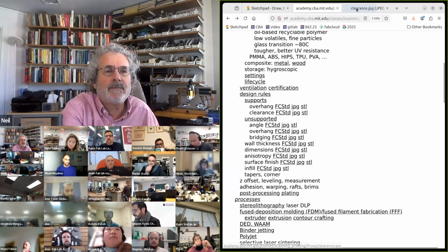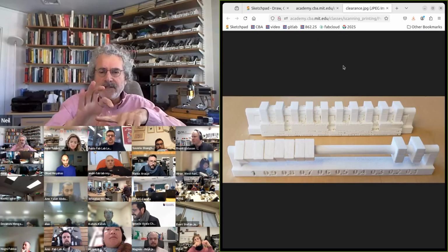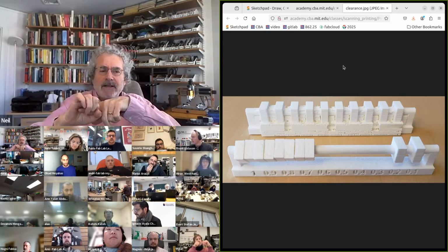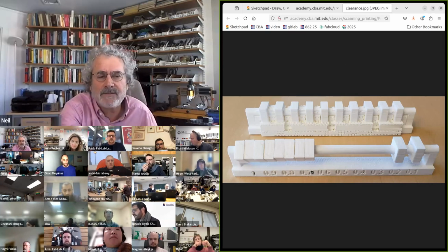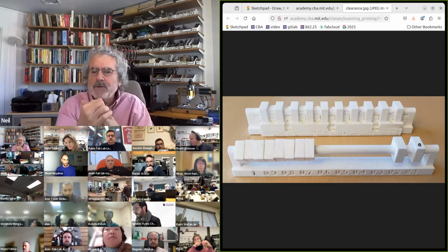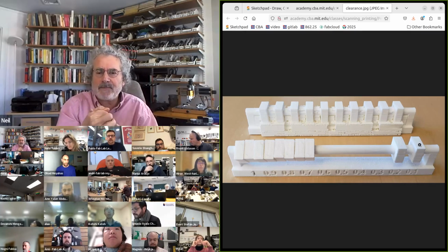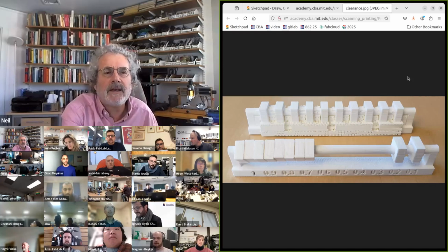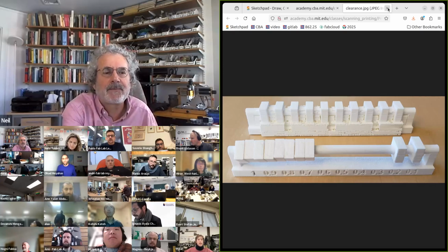Then here what I'm testing is these are a series of parts getting a smaller and smaller clearance, and these are in fractions of a millimeter. And all of these released, but when the gap got that small, that was too small and those didn't release. So the next design rule is how close a part can be and not bind.